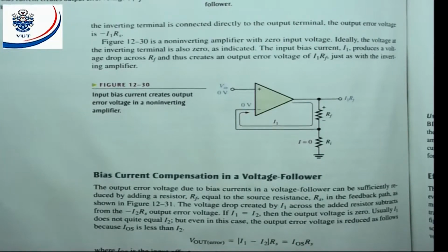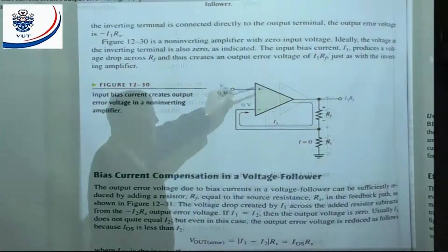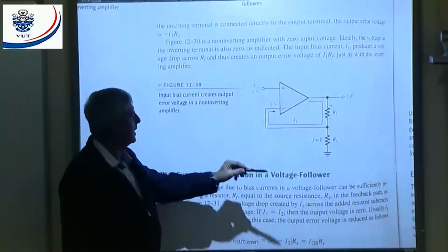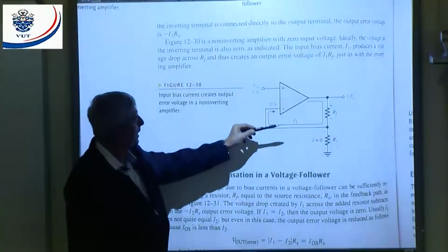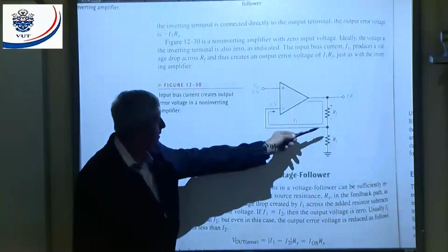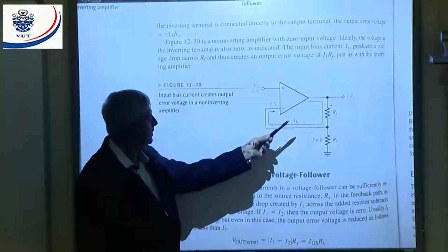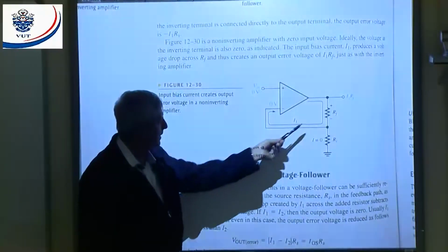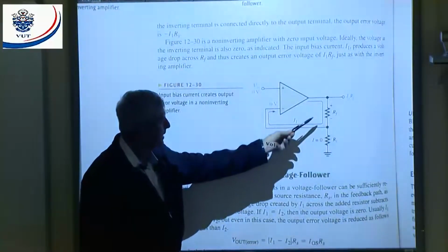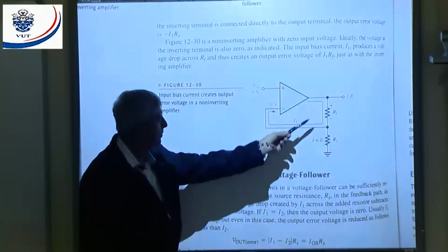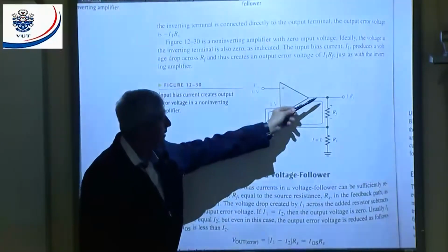And by adjusting that, we can adjust our offset voltage to compensate. That means this IC has the facility to adjust it to 0 output voltage. That means I got 0 in to get 0 output. That's the facility on the device itself.